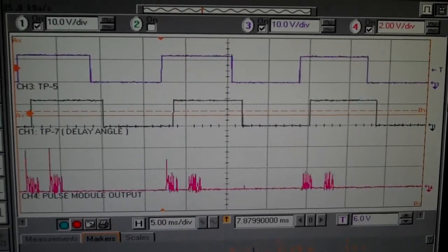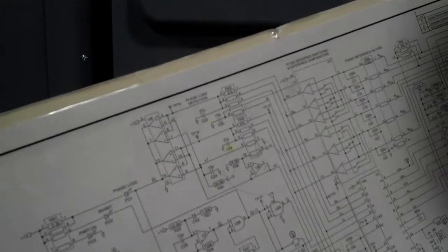The next thing on the circuit, we're going to take a look at the phase loss detection circuit. And this is the way it works. We basically have a window comparator, we have 2 thresholds, and then the 2 phase loss signals will have to be within the thresholds. This is something that we've done before.